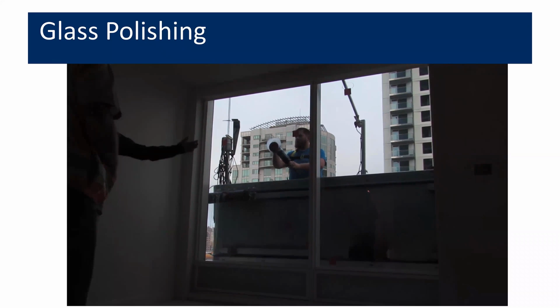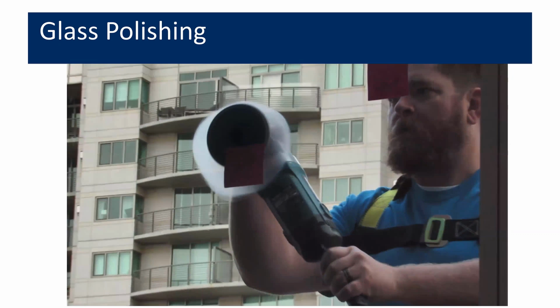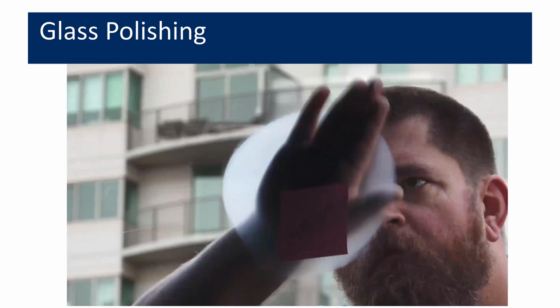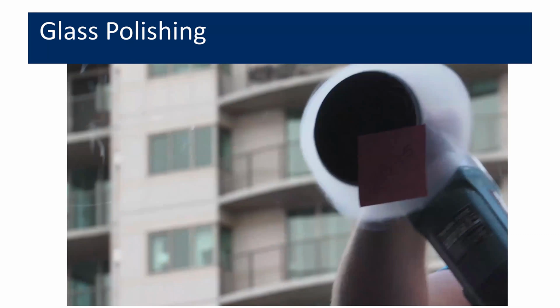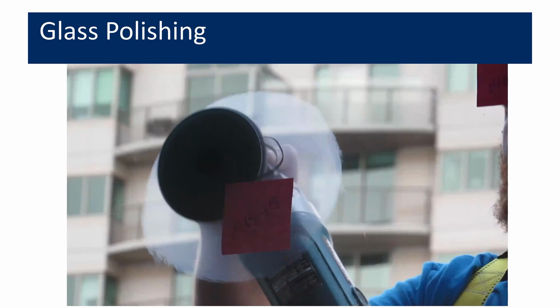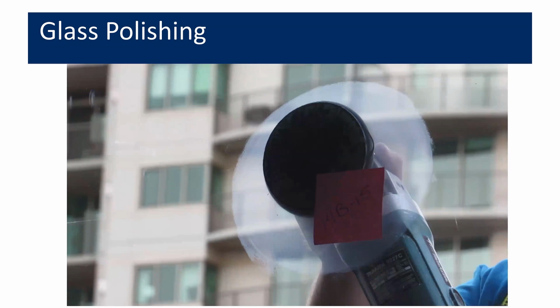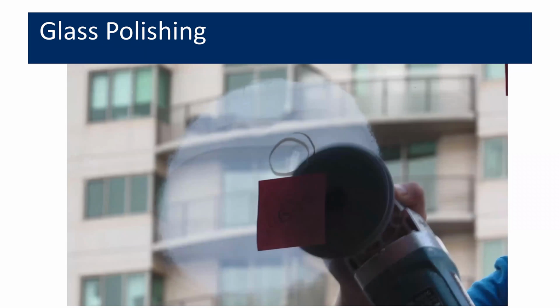And you can see that the worker is starting with a relatively coarse grit sanding disc to try to get to the bottom of a marked blemish. And then he's mounting progressively finer sanding discs on the end of the polisher. He's feathering the repair area out to minimize any distortion.